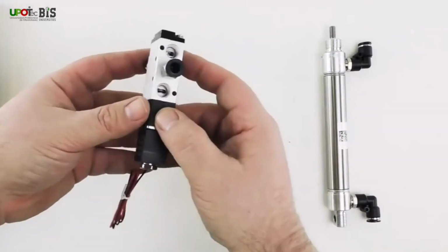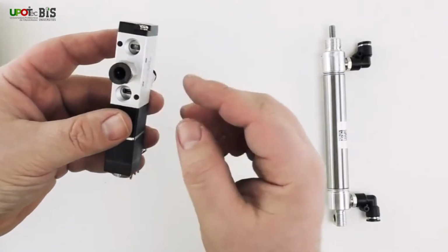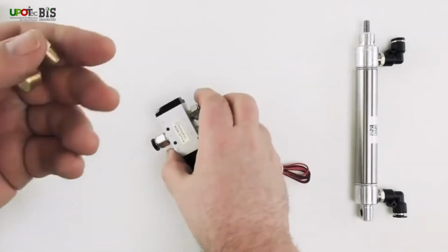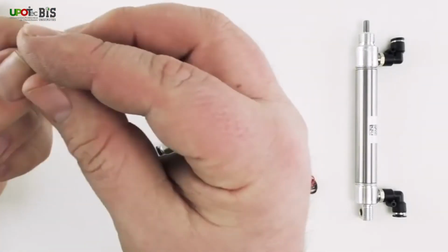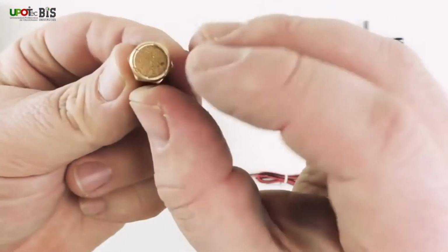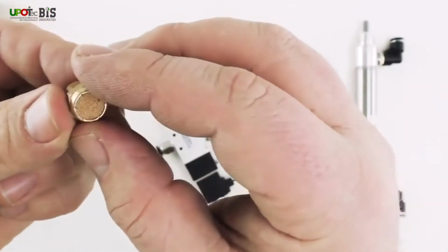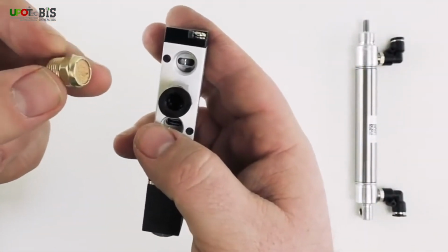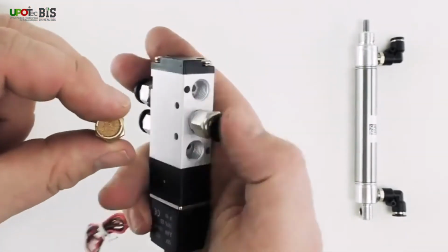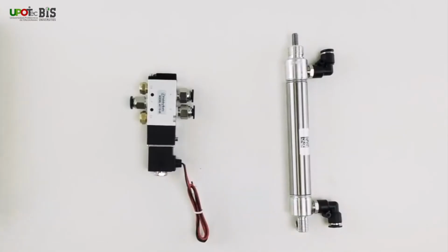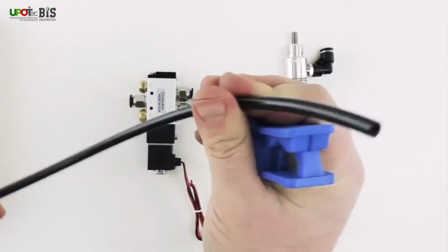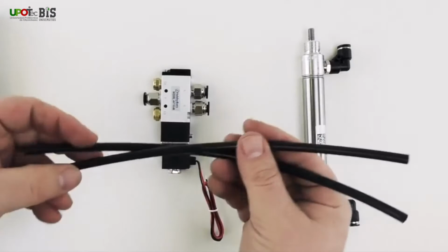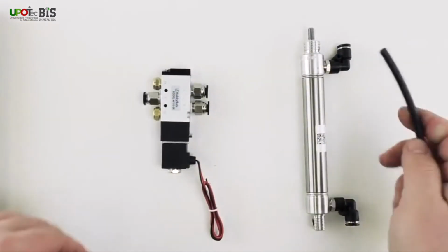The last thing that we need to do for our solenoid is install some mufflers into the exhaust ports. For the exhaust ports of the solenoid, we have these 2 breather vents. You can see that these fittings are threaded on one side, and they have a muffler on the other. The primary purpose of these is to block debris from entering into the exhaust ports of the cylinder, but they also help to slightly muffle the sound of the exhaust. For this, we're going to be using some 1/4 inch polyethylene airline. This is the most common type of airline used in this sort of application. So we have these 2 pieces like that.